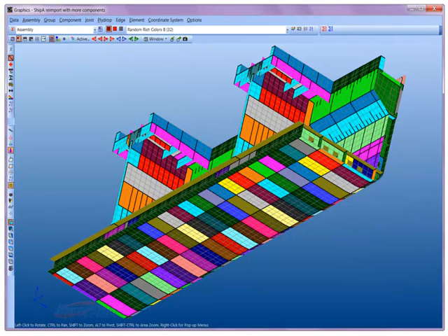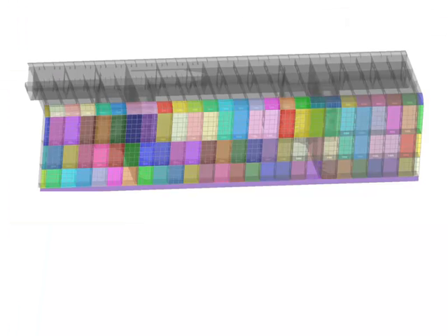A typical FEM of the hull has only a few elements representing each individual panel bay. Modeling technique 1, the smeared equivalent stiffness approach, is used. In this transparent view, each individual panel bay can be seen spanning the underlying transverse frames.